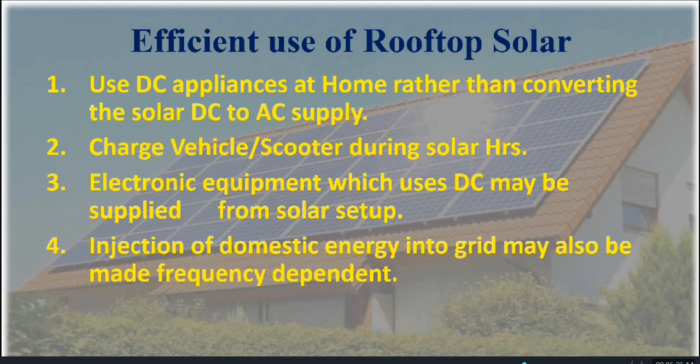If the injection of solar energy becomes frequency dependent, that is, whenever the frequency of the grid goes down, if somebody injects energy into the grid at that time, they get more tariff. As a result, the customers will be encouraged to inject power whenever there is a low frequency in the grid, and that will also help the grid to increase the frequency whenever the frequency comes down.